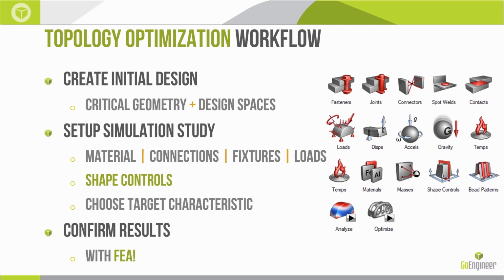Now, some topology optimization software has something called like a slider. So yeah, I say I want to target 70% material reduction, but it's going to deliver anywhere from 0 to 80%. And I just adjust the slider. I don't even have to rerun the study, which is very nice.